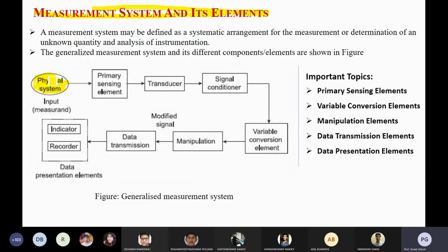If you see what a pressure sensor is, we are actually using crystals, like quartz crystals. If you apply some pressure across the quartz crystal, you can find some voltage; that voltage will be generated, and you need to sense that voltage. Whatever the physical quantities are, if you are related to electrical measurement, the signal from the physical quantity should be converted to an electrical signal. That's why the transducer is important. A transducer is an example of a sensor that can convert a physical quantity to an electrical signal.